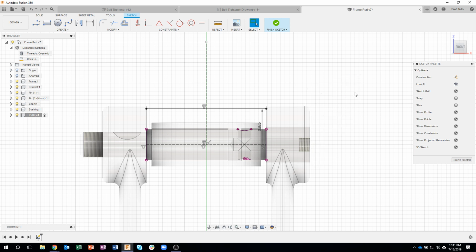So I'm just in my workspace right now, I'm just going to right click and drag straight up, and you're going to see it's going to repeat the last command, which was offset. So instead of having to go to the menu over and over again, I've done my offset, I just have to right click straight up, and I get my offset command again. So I'll say that one needs to be 15 sixteenths. Okay. And so I've just offset it 15 sixteenths. I'll right drag straight up again, and it's going to do the offset again.